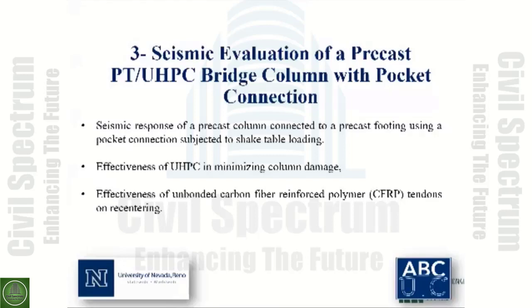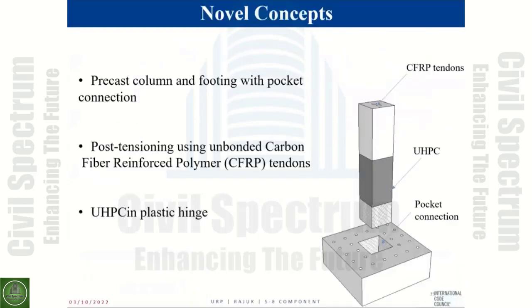So this is a departure from the design philosophy that Professor Itani mentioned, where damage is accepted. Also, a lot of times in bridges, especially in the near-fault region, the issue we have is that the bridge has permanent lateral displacement, to the point that the bridge feels unsafe and you would have to shut it down to traffic. So here we use some post-tensioning using carbon fiber reinforced polymer tendons to recenter the column. So these two innovative ideas were incorporated in this project.